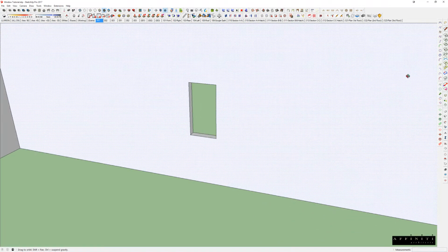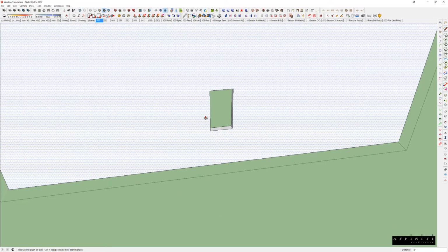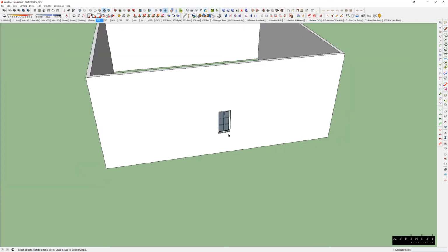And again, hiding rest of the model, you see I just cut out essentially my masonry opening. So when they build it, this is essentially what they would build, the masonry opening, and then the windows themselves have the 2-inch buck built into it. So my 2'6" window has the 2 inches extra around it. So it kind of fits with our construction drawings as is. And so now we're building a masonry wall that has a masonry opening. And you can see my window is there. It looks pretty identical to this.